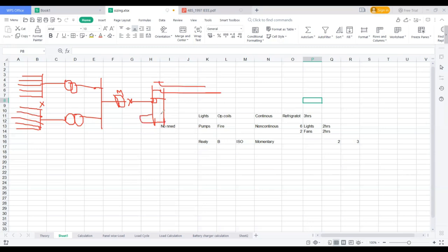So we have not come up to the protection level. For time being, I'm explaining here. So wherever the breaker is there, we are considering that this is a 33 kV panel. So all these control and relay panels have all the relays and coils inside. So we are having 33 kV panels and 220 kV panels 1, 2, 3, 4, 5, and 6 plus one bus coupler panel and one this panel